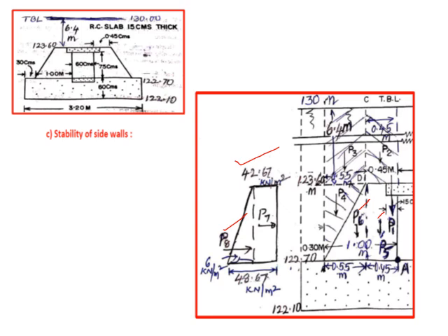Then what is the lever arm for P4? So that means you can come down till here, which is 1 meter. So you can deduct this portion, 1 minus 0.55 by 3, or you can take 0.45 plus 2/3 of 0.55. So what is lever arm for P7? P7 is this, half of 0.9. What is lever arm for P8? It is one third of 0.9.